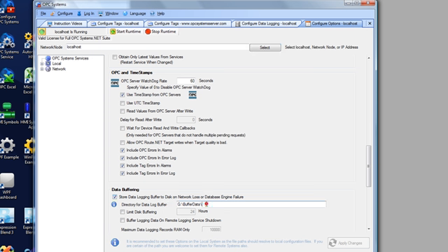You then simply specify a directory on your local hard disk to buffer to when you have either a network loss or database engine failure. So in either setup of monitoring remote OPC system service tags or logging to a remote database engine, as long as we have this feature enabled on all of the services that we're logging from or actively logging to, then you will lose no data on a temporary network loss.